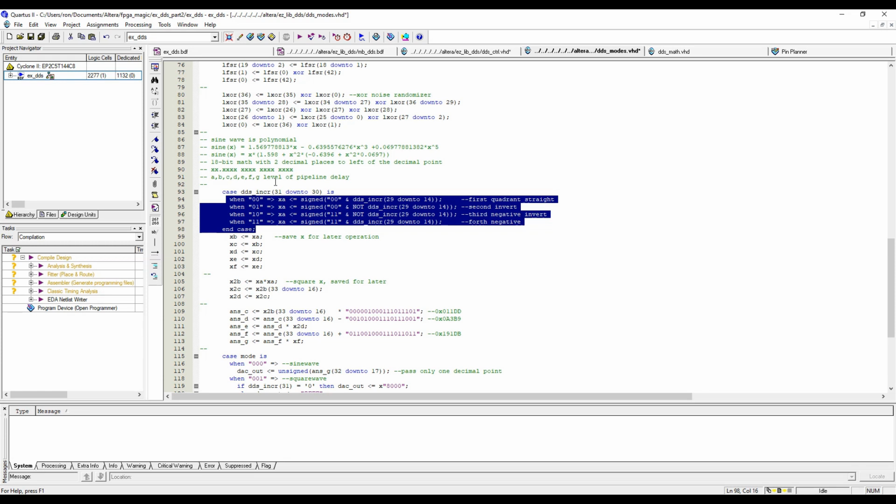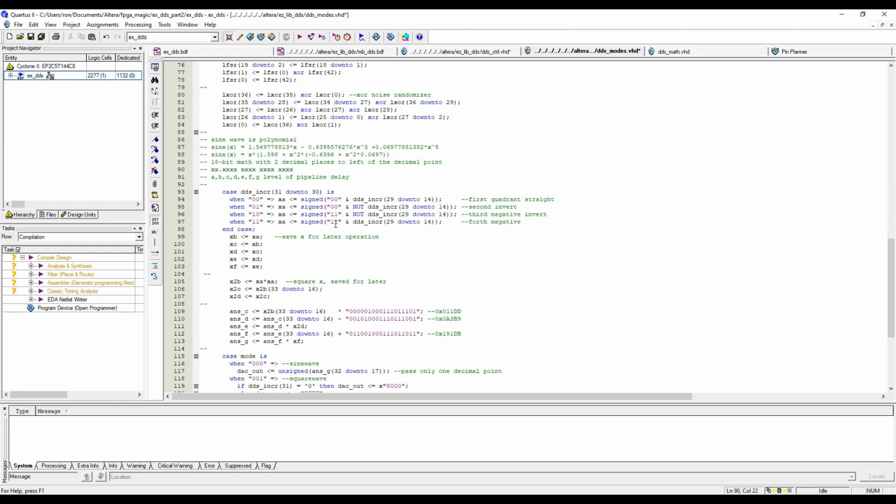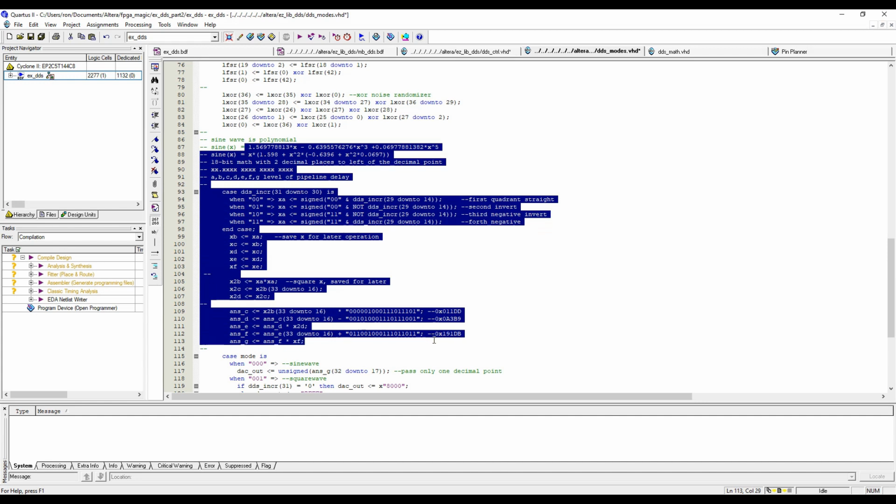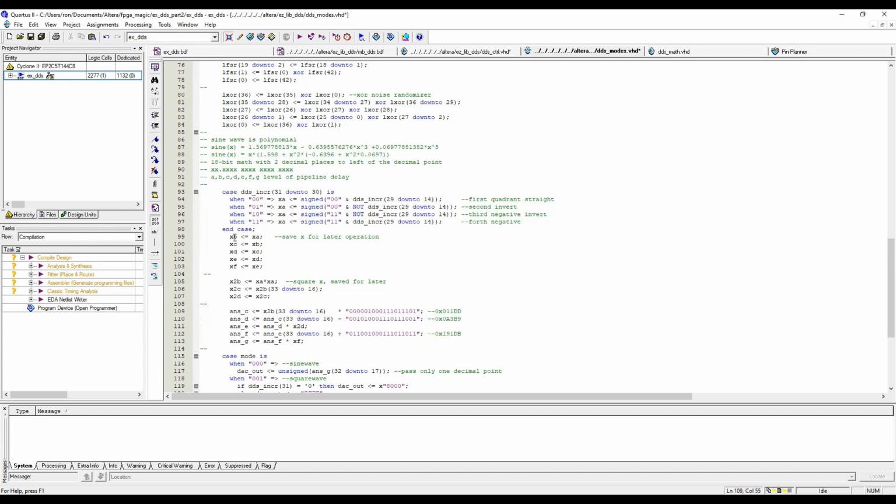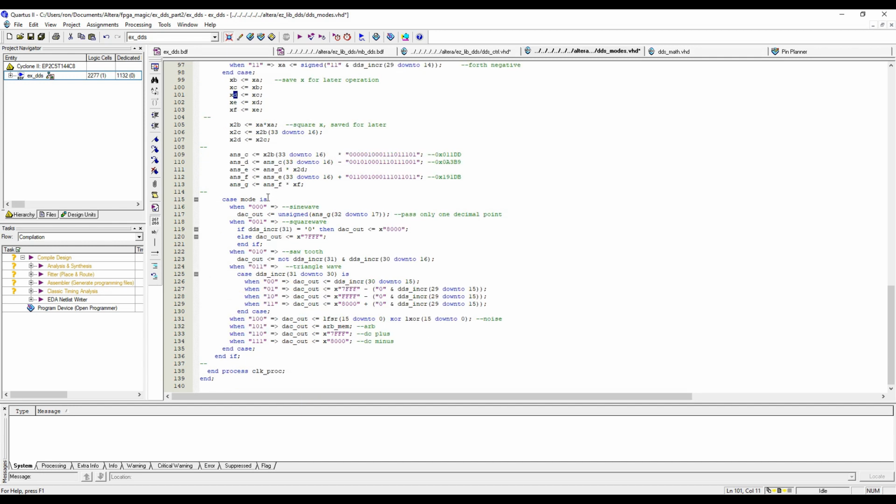The sine wave is generated by a fifth-order polynomial, which provides about 14 bits of accuracy. This polynomial is heavily pipelined, as you can see, where the letter defines how deep in the pipeline it is. The other outputs are derived from the input phase counter.